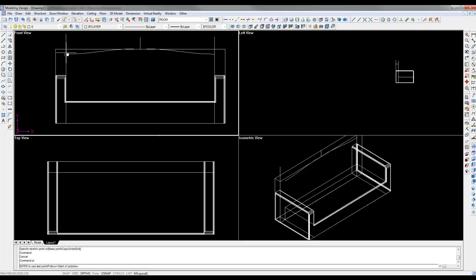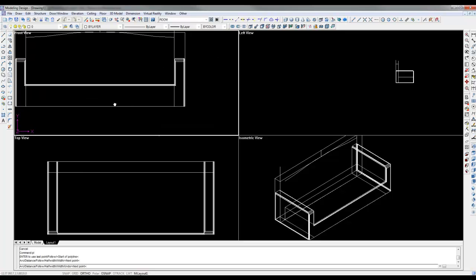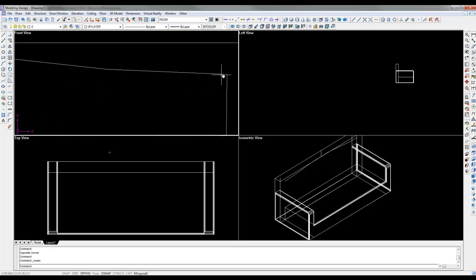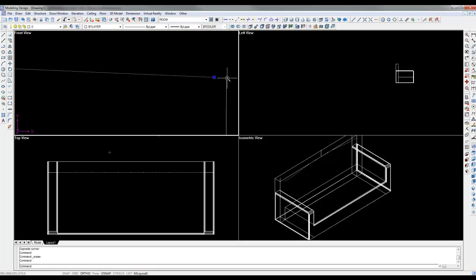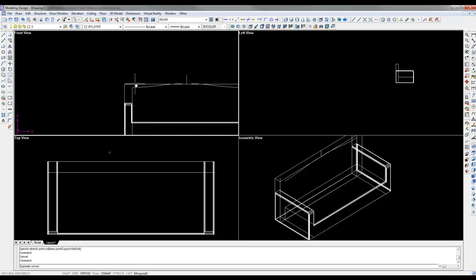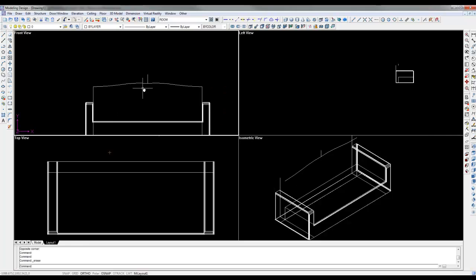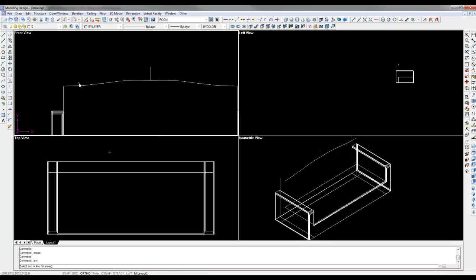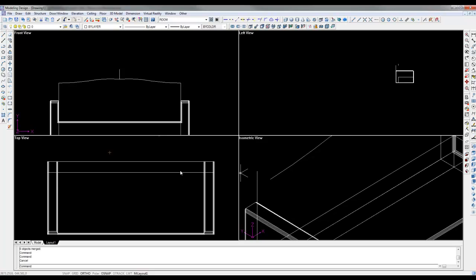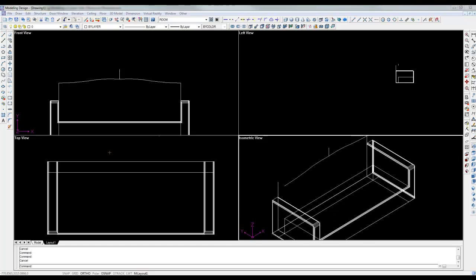So now, using our polyline tool, we just trace out the shape there to here, and once again we can just use the join option again. So this one has to snap to the point over here. There we go. And that one I think is joined. So I'm just going to delete that guide shape I drew earlier, and then we can just use join again. 1, 2, and if it doesn't join, we just have to find the reason for that happening.